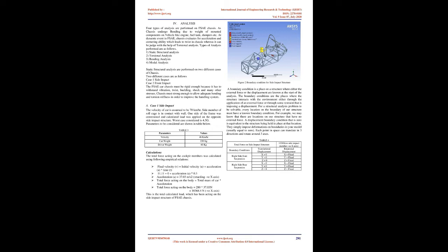Beam elements are normally used to represent tubes. The assumption made in using beam elements is that the welded tubes have stiffness in bending and torsion. If truss or link elements were used, the assumption being made would be that the connections do not offer substantial resistance to bending or torsion. Another aspect of beam elements is the possibility of including transverse shearing effects.